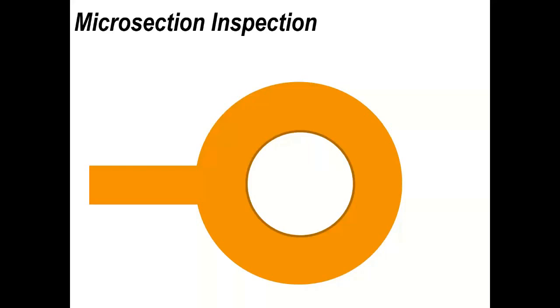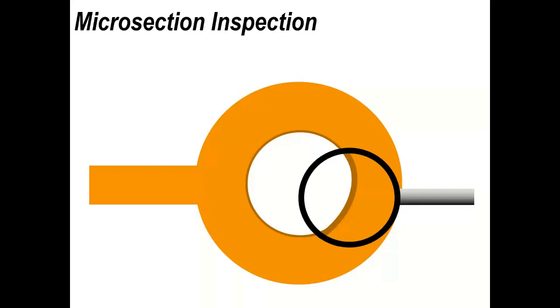I've already gone through halfway through the hole, if you like, but I didn't have a drawing to show that, so I just show it with this. I take the section and then I microsection it through from the top or the bottom. And what this allows me to do is to see whether that defect that I've seen initially is representative of the rest of the plated through hole ring.